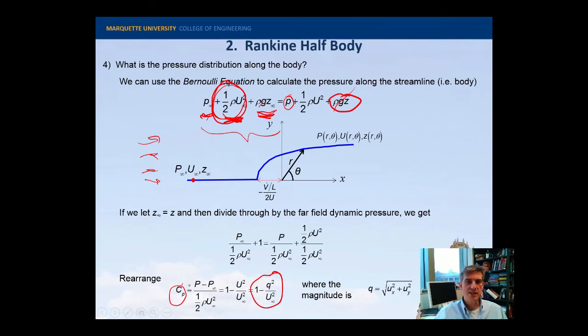Okay. So you can see that this coefficient of pressure for any velocity is going to be equal to something less than 1, right? If the velocity is 0, we would get a coefficient of pressure of 1. That makes a lot of sense. If the velocity is 0, we're at the stagnation location, and this has gone to 0, and so the far field pressure plus the dynamic pressure, that's the maximum pressure we can get here, is equal to the local pressure. And then as the velocity increases from stagnation, one would expect the pressure decreases. And so the pressure could decrease all the way to Q goes to infinity, that would be 0, right? So we expect C sub P to vary between 1 and 0. That makes a lot of sense. All right.